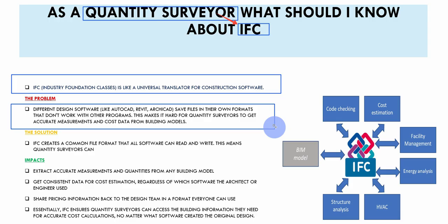We will also have a look at that one, maybe in later courses: how you decide at which level of estimates you are going to work. Because sometimes different people try to go into details even when the project is not at that level of detail. Then you make a lot of mistakes, because you want to do a 100% cost estimate when the design is still at 30% progress.